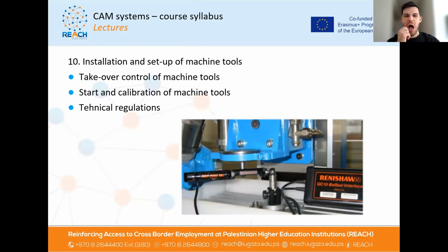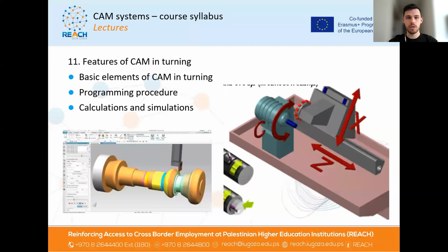After that, once the students have this whole story of producing the part, we give them information on how this CAM program is translated to the existing machine, and actually before that, how this machine is set on the company's floor, what the main regulations are, and how to calibrate the machine tool and everything prior to using it.